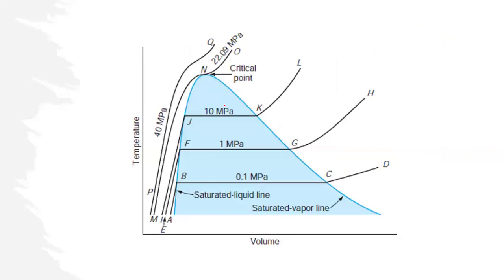Now, using this graph, we spoke about A, B, C, D. Remember, point A is where our temperature was 20 degrees Celsius, if you still remember. And then our temperature over here is going to be 99.62 degrees Celsius, right? And if we look at here, this is the equilibrium. So here at equilibrium, we can tell that there is a completion of the phase change, meaning here we have the saturated liquid, and on this side we're going to have the saturated vapor.